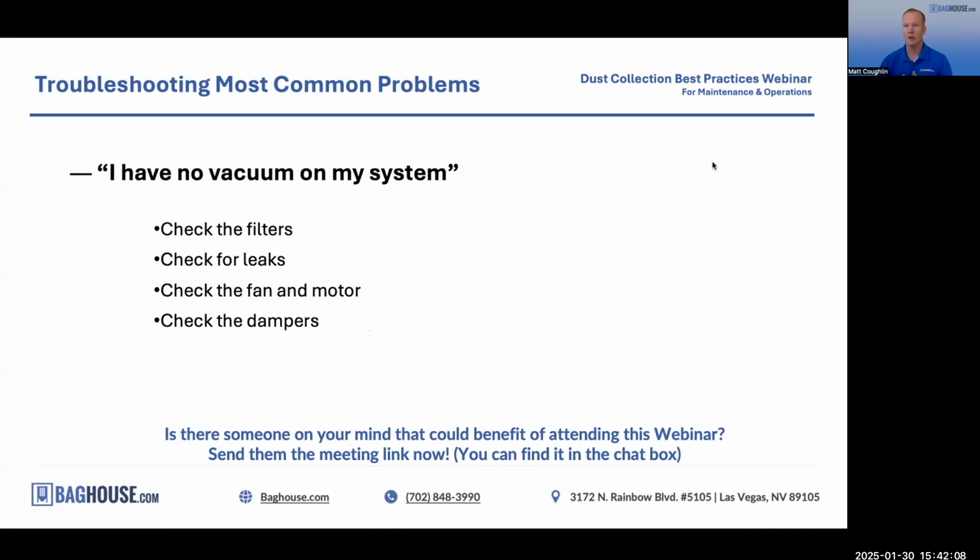So we'll look at the fan itself just from a basic maintenance and PM perspective and say, how does the fan wheel look? What's the fan RPM? We can stick a probe just upstream and figure out what the actual airflow and the vacuum pressure of that fan is, and make sure that it matches up to what it should be for your system.